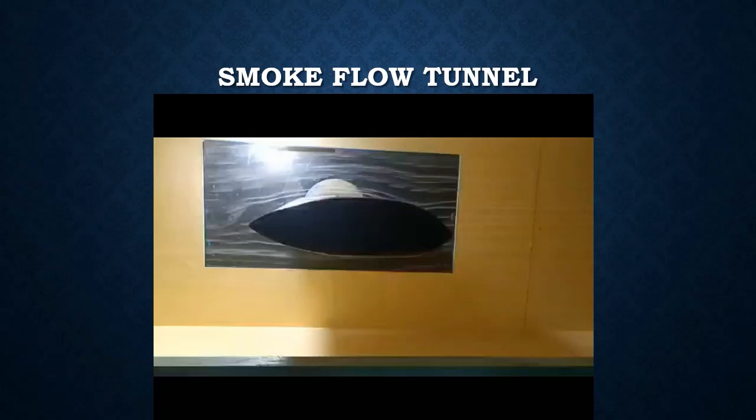Here all the smoke comes out from the smoke rake, and the smoke flow follows as a streak line. So it is called streaks. We should not call it a smoke filament, it is nothing but streaks. Streaks come out from the smoke rake, where the streamlines are coming upstream of the contraction cone.